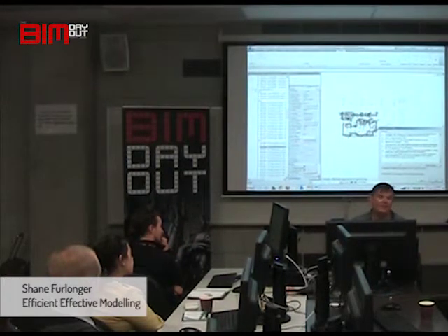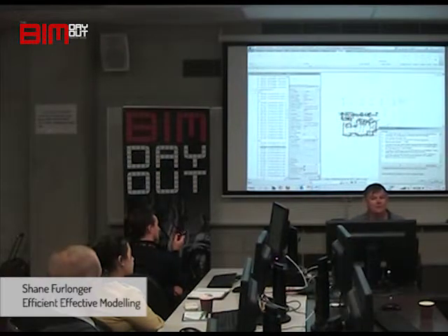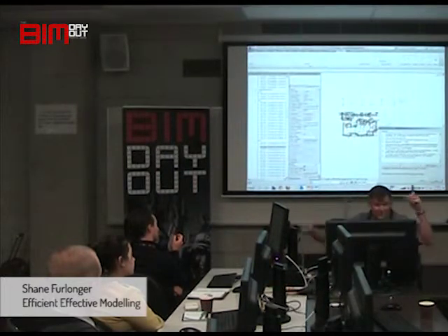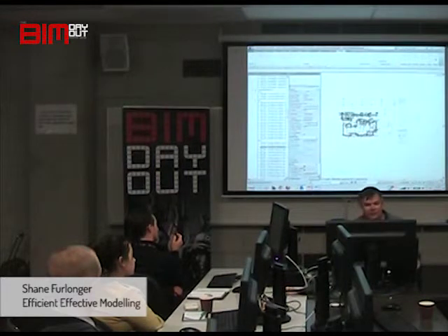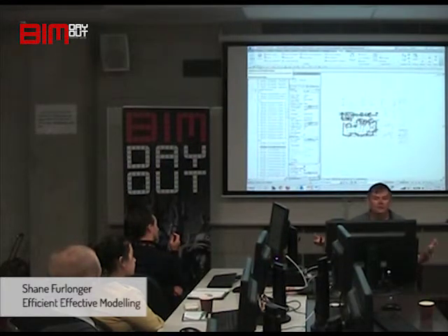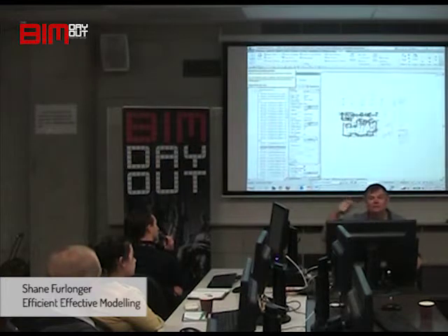So you've actually got to go into the sketch to find the line that's off axis. It doesn't tell you which line's off axis. It just tells you a line is off axis. So then you've got to find it. And that can be painful if your sketch goes in a funny shaped building all over the place. Because you can highlight the whole thing and go, and it'll just give you the one warning for all the lines.